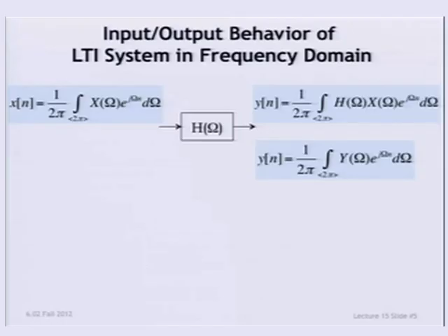And then we saw how to apply that to a system. We have an LTI system, therefore characterized by a frequency response. We first introduced the frequency response as a way of thinking about what happens to cosines. Put a cosine in, and you get a cosine out that's scaled by the magnitude of the frequency response and with the phase shifted by the angle of the frequency response. And then we went from cosines, or in parallel, we talked about exponential inputs, so inputs of this type.